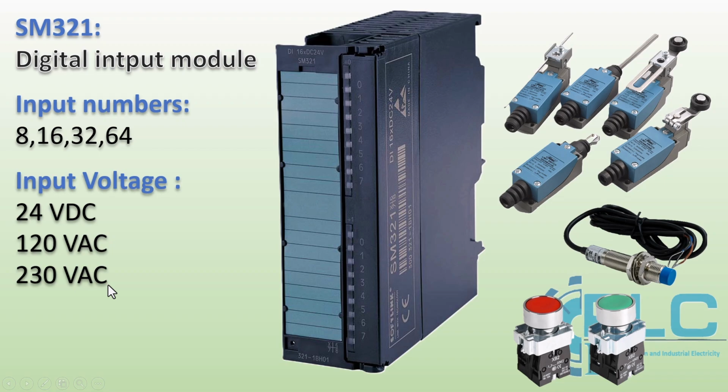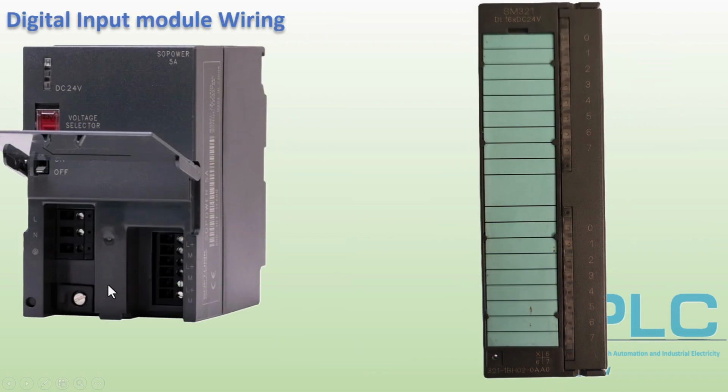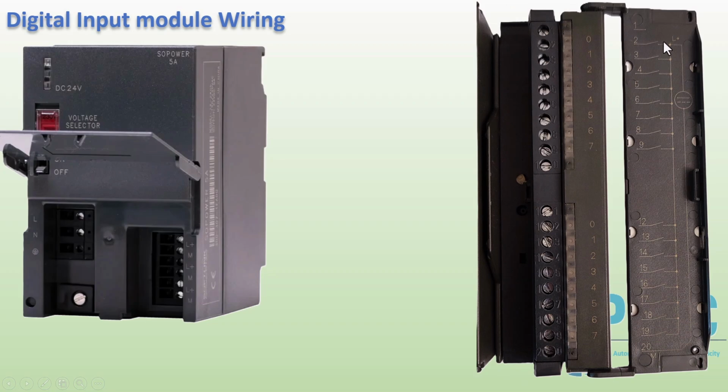Since we will start programming in the next video and test our project with real hardware, it is crucial to understand the correct wiring of the SM321 digital input module. This module has 16 digital inputs and operates at 24-volt DC. Now, let's take a closer look at its wiring configuration. When you open the module cover, you will find a wiring diagram printed on the inside. This diagram guides us on how to correctly wire the module to ensure proper operation.